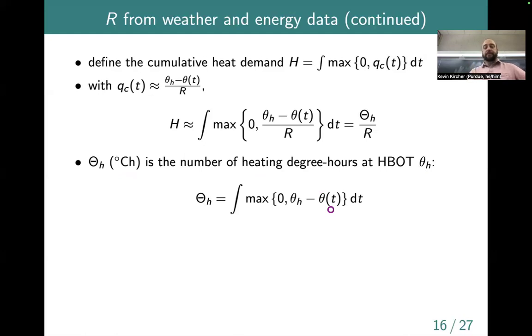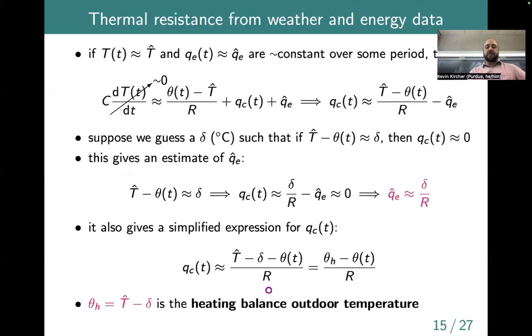Yes? What did HBOT stand for? Sorry. HBOT was from the last slide, heating balance outdoor temperature. So heating meaning not cooling, right? We're thinking about winter, and then balance, really, it's sort of the outdoor temperature at which the heating demand is zero. So, okay.